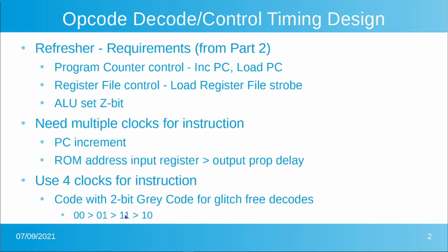But if you look at it bit-wise, this only changed the bottom bit, this changed the next bit, this one changes the bottom bit, and then back to here, because it'll loop around forever, just changing one bit. So there's a big value in having that. If you generate something that's a couple of clocks wide, you don't get the potential glitch between the counts.